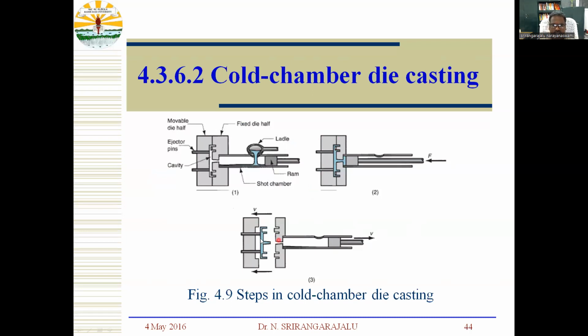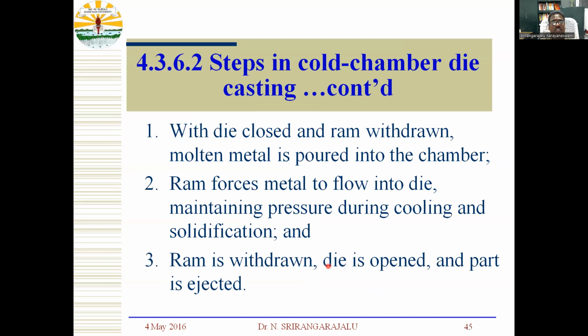After the solidification, the movable die is moved, and there are ejector pins. With the help of these ejector pins, we can remove the final component, and then we can carry out the required finishing operations. These are the steps in cold chamber die casting.